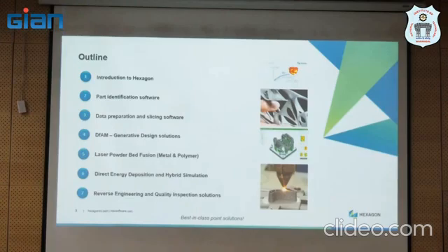different technology, and it has other benefits like investigation of what material is used, what kind of coating, and how it is manufactured. So in re-engineering, we start with the selection of an existing component. Then we try to optimize something. It might be from the lightweighting point of view. It might be from the topology optimization point of view or the performance point of view.